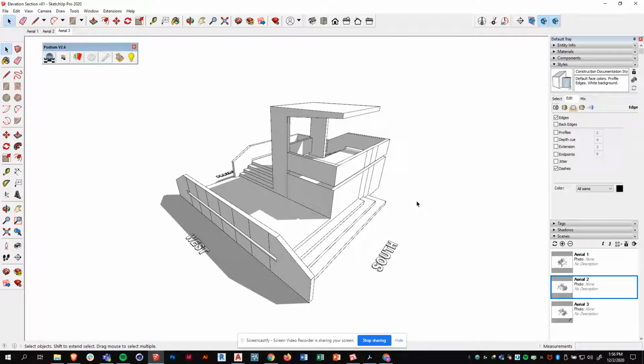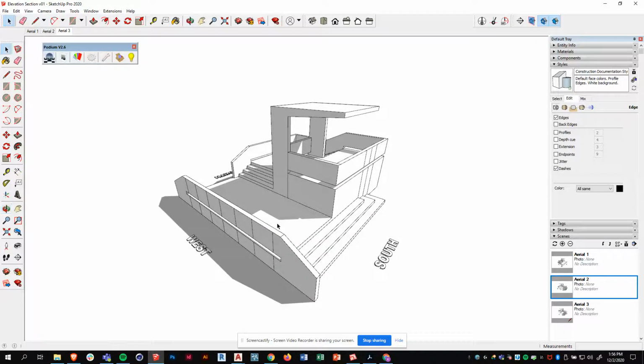So while a floor plan will show you what's happening from the vantage point overhead, looking down with your building sliced through horizontally, section cuts go the other direction, and it's as if you're standing in the building, looking at the cut. So I'll illustrate that for you here. I'm going to show you the section cut that we're going to make together, and then I'll show you how we're going to get that cut, not with any three-dimensional software, but just with the elevation and the plan that we already have in CAD.